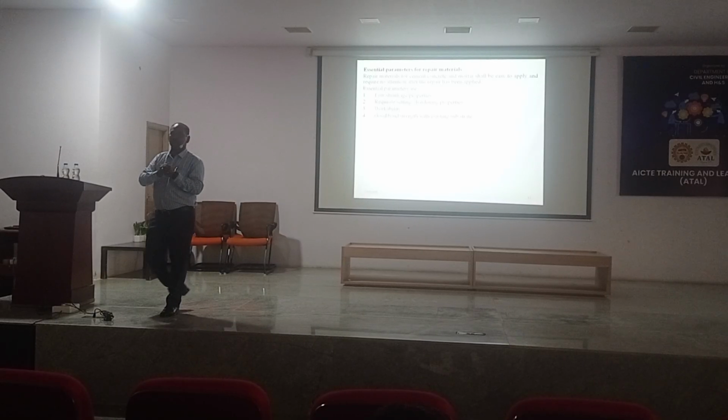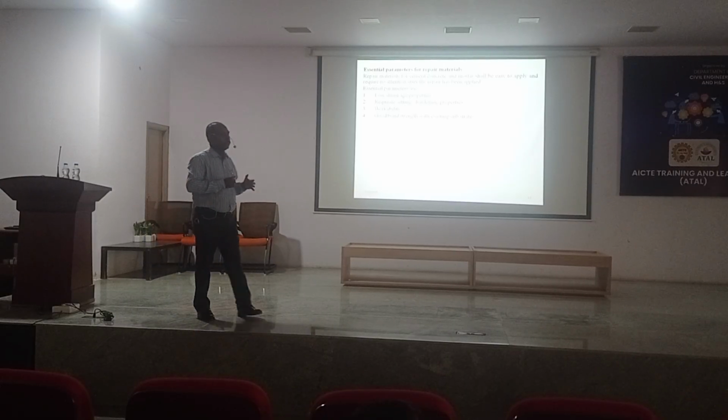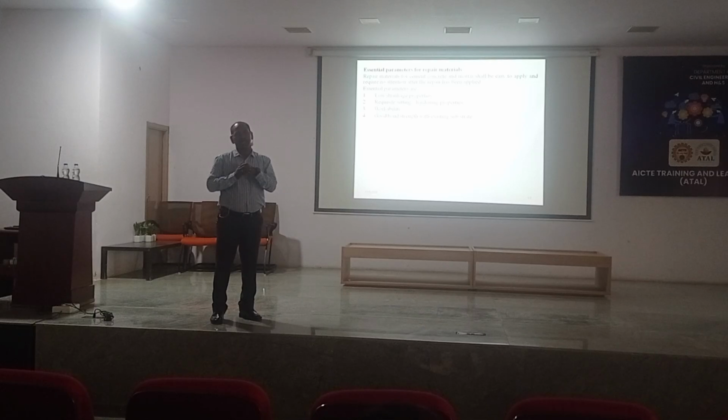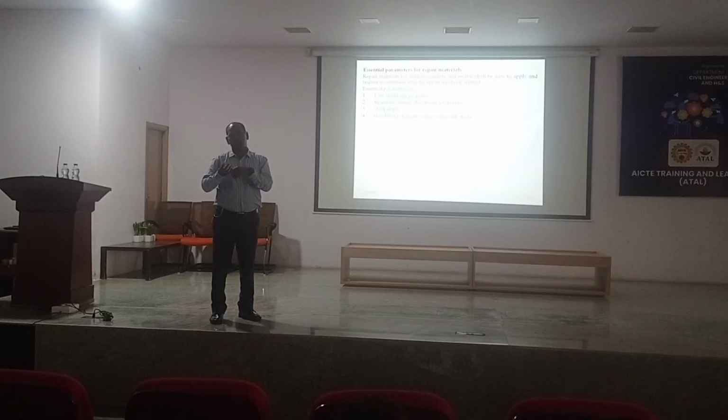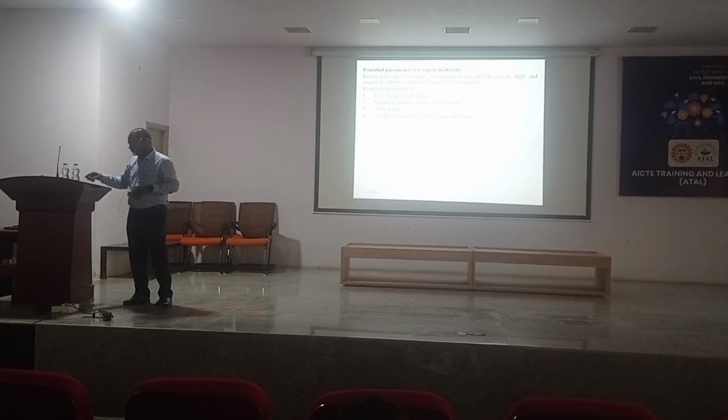And there are also many problems in that case. If the old strata is dry and they put the mortar, the water available in the mortar will be absorbed by the old one. Once that water is absorbed by the old one, there is no water for hydration, and the repair is of no use. Therefore, you should consider all these aspects while selecting the repair material.